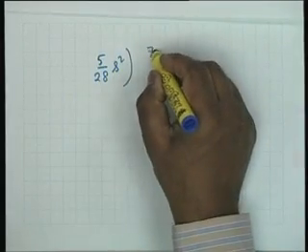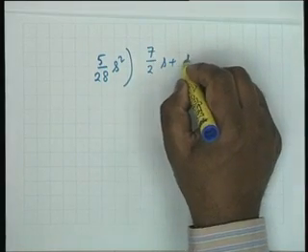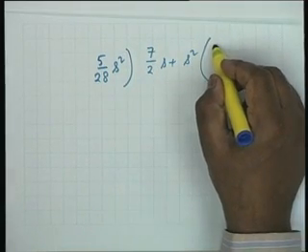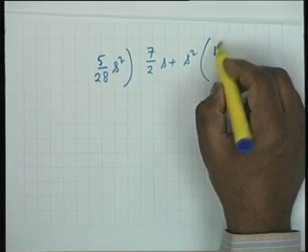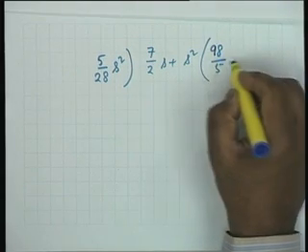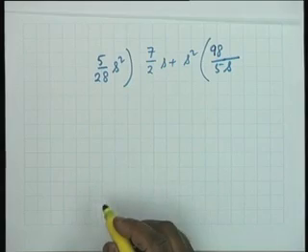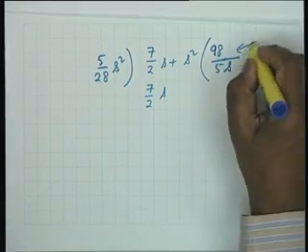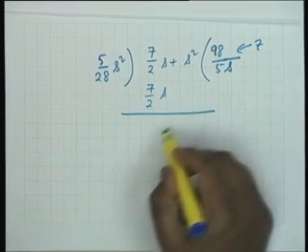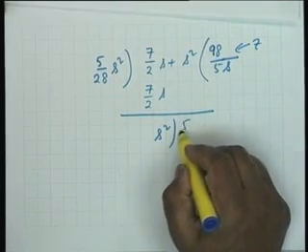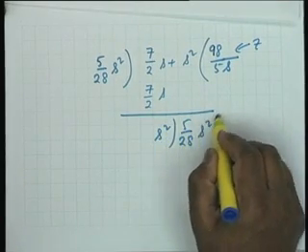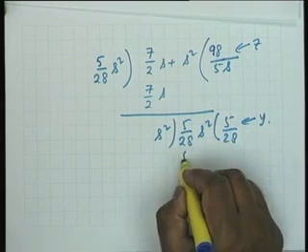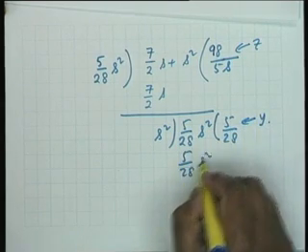This divides 7 by 2 s plus s squared, and the quotient is 98 by 5s. Oh, that's good. Yes, okay. 7 by 2s, and this is an impedance. Remainder s squared. The last step is very nice. 5 by 28, and this is an admittance. 5 by 28 s squared. The remainder is 0.